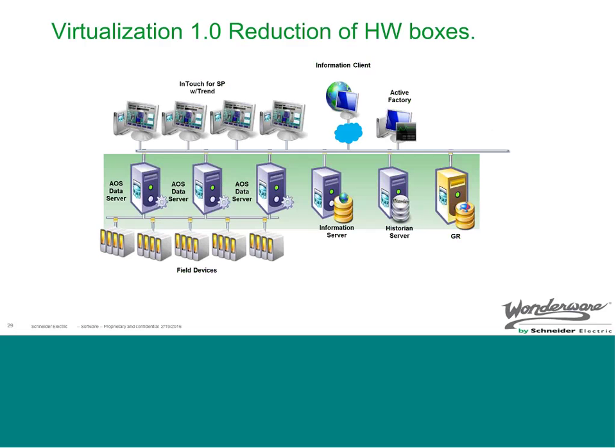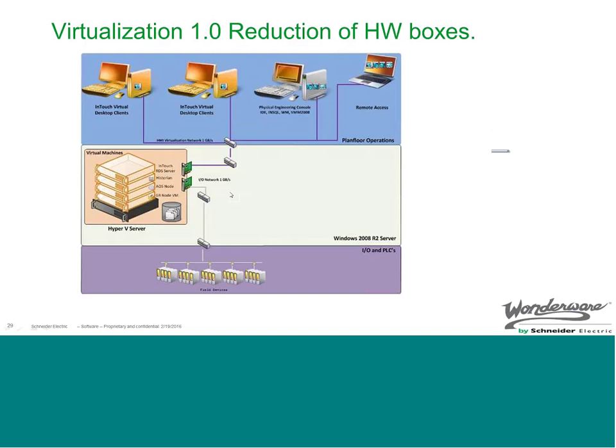You might have a terminal server that the thin clients or workstations are accessing for their HMI. You might have a reporting portal, your historian database, your development database, and your configuration database. So instead of having, in this case, 6 physical servers with 4 or more workstations, you can consolidate that to everything running on a single physical server, and then everything else becomes a thin client.